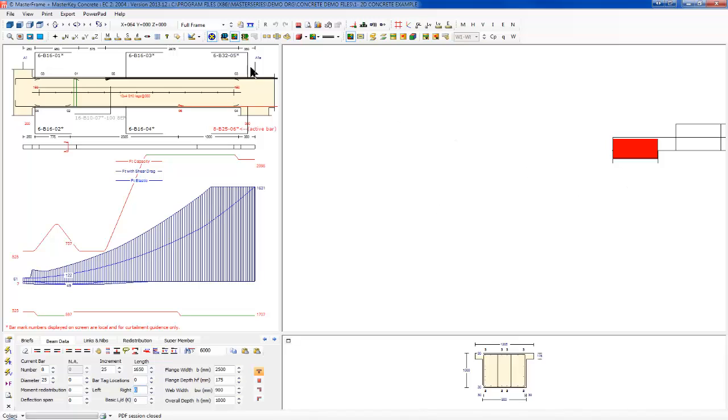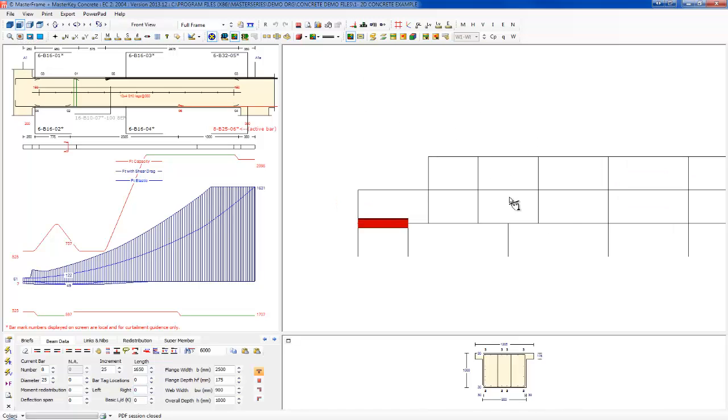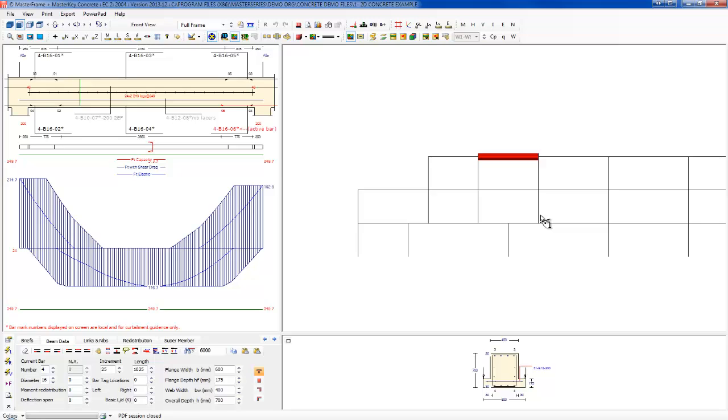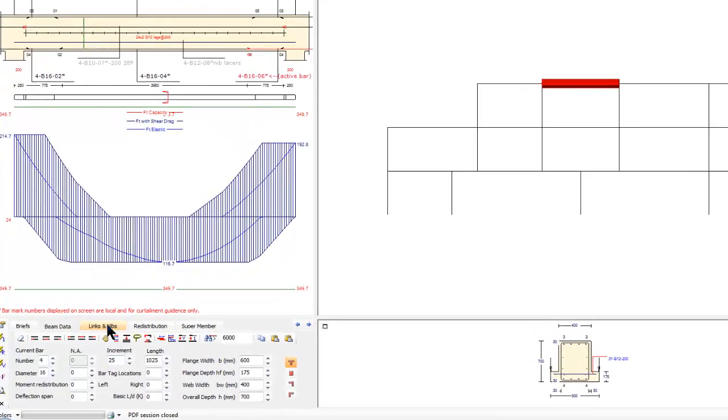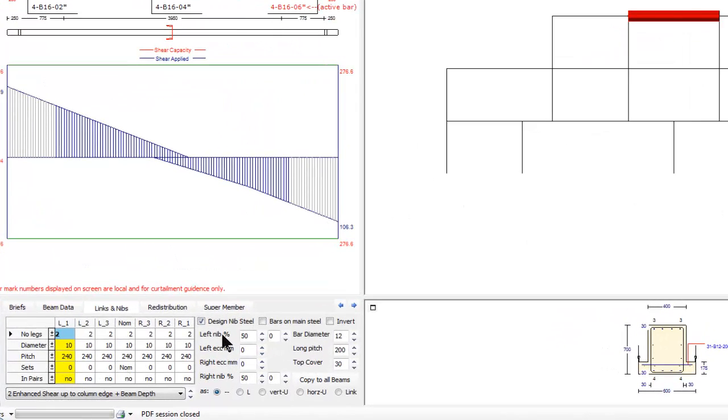I'm going to come back out here and look at my frame. And the one thing we didn't talk about was, do you remember the top floor was inverted T-beams? They're great. Obviously, it kind of messes around with your reinforcement in that your compression flange is not a flange, but just the web and over the supports and things like that. And if one must, one must. But more importantly, we can apply loading onto the beam. So what we're saying is that half the load goes onto the left nib and half the load goes onto the right nib.